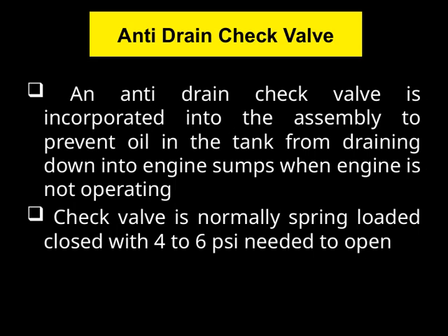An anti-drain check valve is incorporated into the assembly to prevent oil in the tank from draining down into the engine sumps when the engine is not operating. This is a crucial feature because it helps maintain proper oil levels and ensures quick, reliable engine startup.